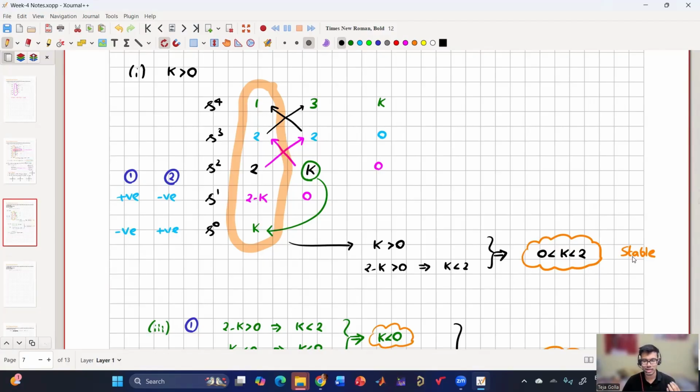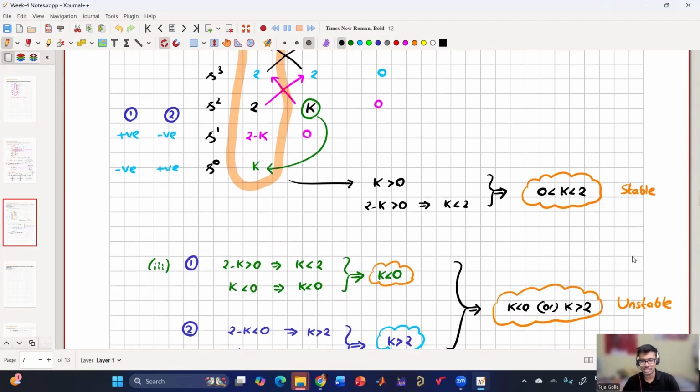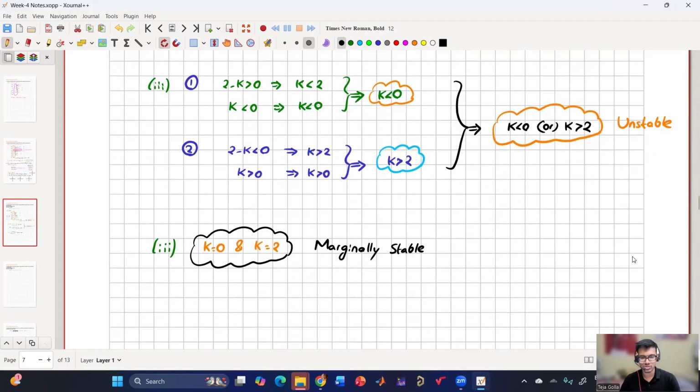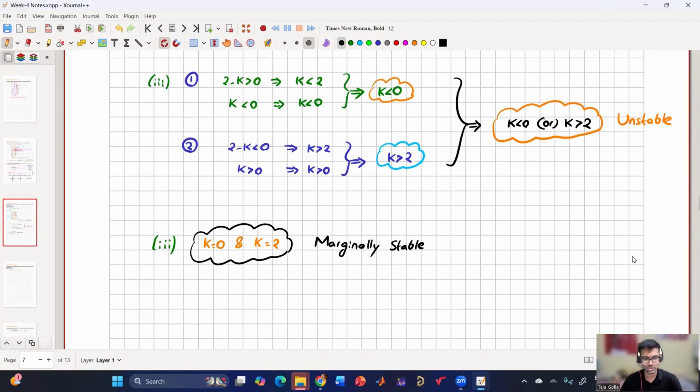Again, this concept extends to root locus, which I'll discuss on Monday, where I change a gain K from 0 to 10. How will the poles of the characteristic equation change? Because in this case it goes from stable to marginally stable to unstable. If I see how the poles vary, that gives me the border value of K below which I have to operate. That is called root locus. Root locus is nothing but how the poles move with respect to a certain parameter that is varying. I'll discuss this in detail on Monday, but I'm just giving a glimpse.